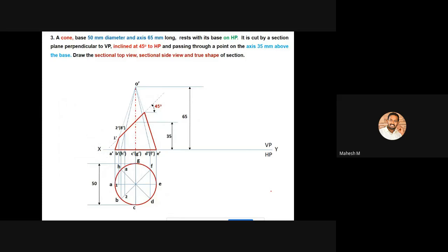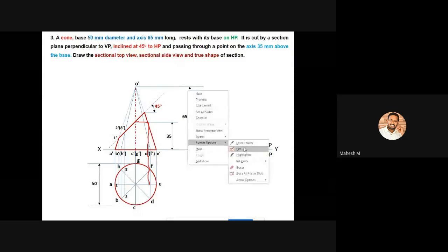So what is the different procedure? You have created 1, 2 and also 8. So the different procedure is that you have to project this cutting point up to the outermost edge. Then you have to project this point towards the horizontal line from O. We already have a horizontal line from O. In some problems like the pentagon, you will not have a horizontal line from the center point, so you have to create the horizontal line. After doing that, you'll have one more corner at this place.